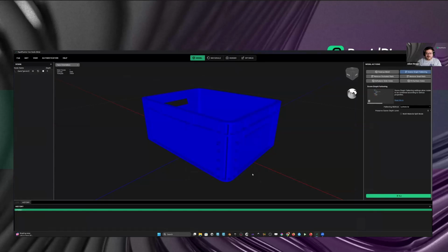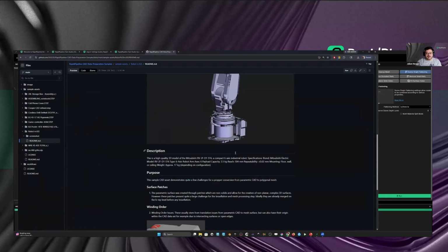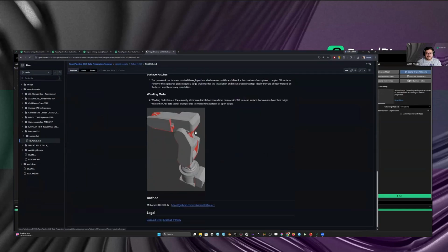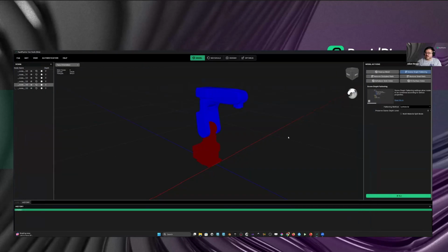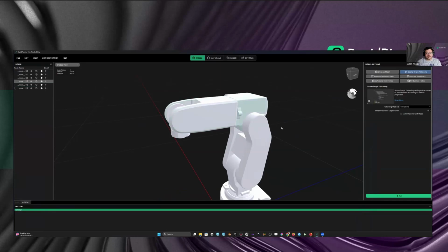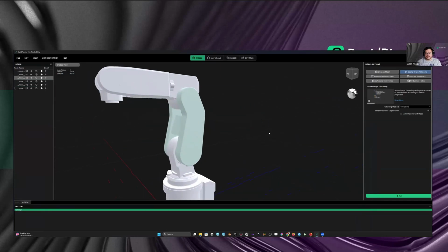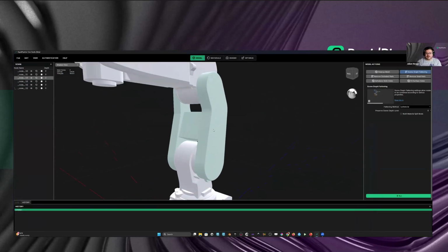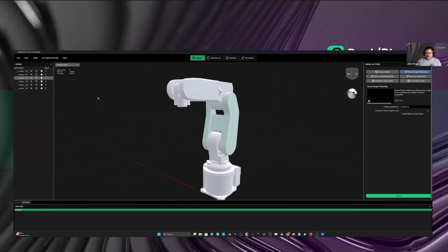So let me just get this file. And on import now we have the sewing. This is a cool example because now we don't have these single face problems with the model, which we would have had with the version imported without the sewing. Now that we have the sewing, we have these great different parts. If I go back to the shaded view, I can see these are actual coherent parts in terms of what happened on the sewing side. So we highly recommend having this feature enabled.